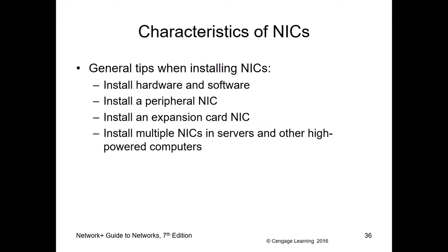All right, general tips for installing a NIC, which most likely you will not do. You need to install the hardware and software. If you remember when we talked about ESD, the electrostatic discharge, if you ever need to install a NIC, make sure you discharge yourself, touch a piece of metal if you don't have that wrist strap, and never touch the components on the NIC or on the motherboard.